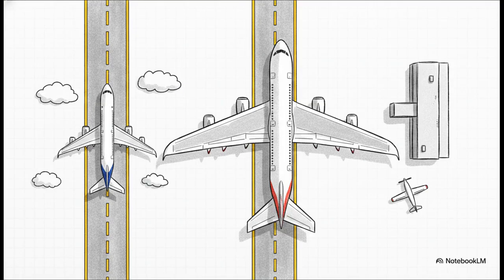To put that into perspective for you, an everyday Airbus A320, a total staple of domestic flights, easily fits into a 3C or 4C slot. That C just means its wingspan is somewhere between 24 and 36 meters. But take a giant double-decker Airbus A380, that beast demands a 4F rating. The F means its massive wings stretch between 65 and 80 meters. If an airport's taxiways and gates aren't rated for an F, that A380 simply isn't allowed to land there. No exceptions. It guarantees those wings won't go clipping buildings, light poles, or other planes.